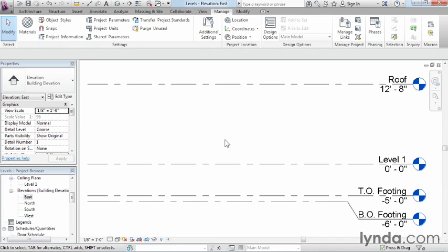But the building that I want to create needs a few additional levels. Now, how do you decide? Well, when you're setting up your project, this is one of the first tasks that you want to do. And what I typically tell people is, if you've got a button on the elevator, you should put a level there. Now, you can have levels for other things.